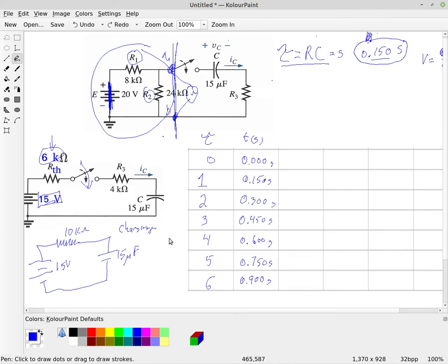And so we end up with a simple series circuit where we have our voltage source and a resistor, right? This is the first circuit we did in the class here. And so the current, we've calculated this current. The current I is simply the voltage, which is the 15 volts, the E Thevenin voltage, divided by the total resistance, which is the 10 kilo ohm resistance.